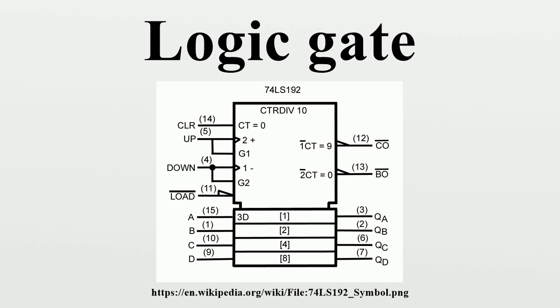The two-input exclusive OR is true only when the two input values are different, false if they are equal, regardless of the value. If there are more than two inputs, the gate generates a true at its output if the number of trues at its input is odd. In practice, these gates are built from combinations of simpler logic gates.